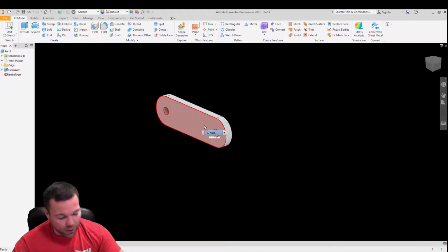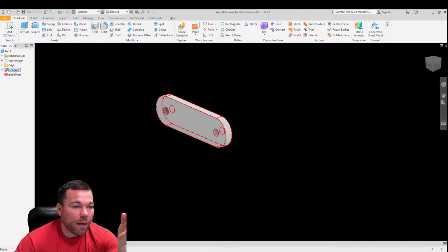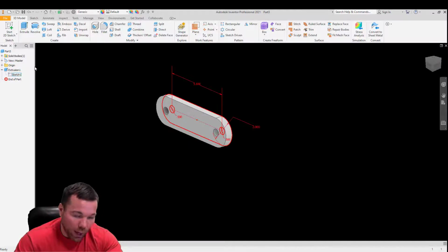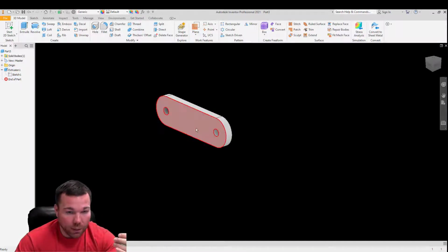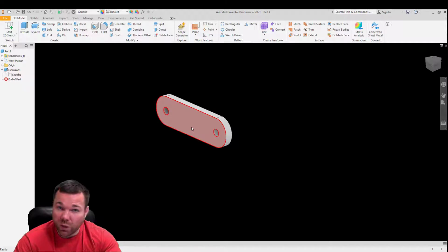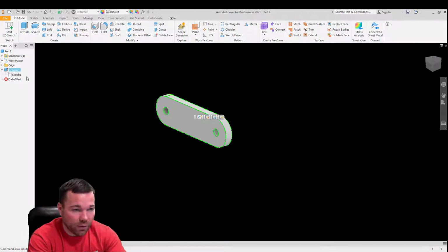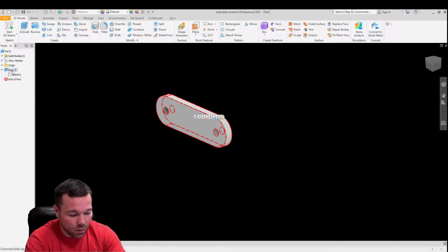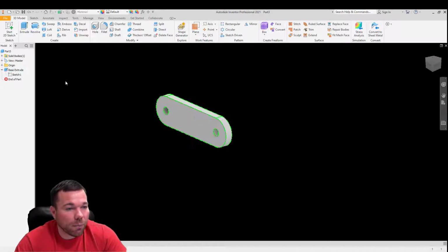All right, so the next page, basically what it's telling you is that this XY plane, and they use the XZ plane, I use the XY plane, but the XY plane in my drawing and also the center point or the origin are the parents to this base feature now. So I'm going to name that. I'm going to call it the base extrude.